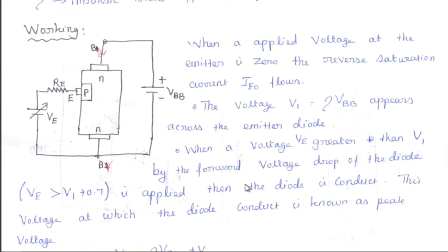Due to these additional charge carriers, the conductivity of the RB1 region increases, that is, the resistance decreases, and the voltage drop across it also decreases. This makes the PN junction more forward biased, which further increases the current, and more charge carriers are injected. So the current IE increases to the value determined by the source resistance. For these cases, the UJT is turned into the on state.